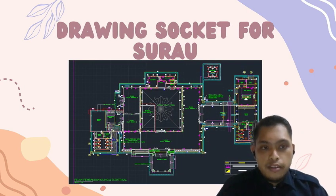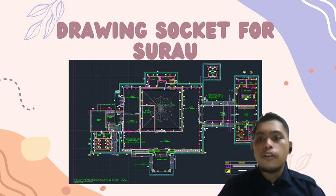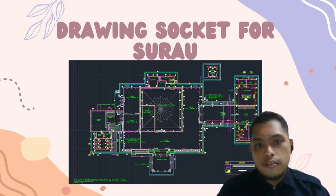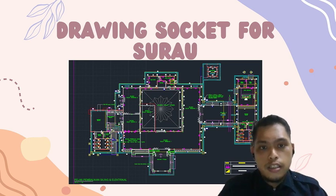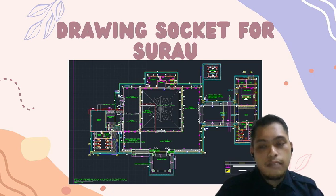Next, from assignment 2, the type of socket outlet that we use for the surau is 13 amp socket outlet. This type of socket also needs a calculation, which needs to be put in every phase, because this surau uses a three-phase system. And it is the same like the lamp, it needs to be balanced.